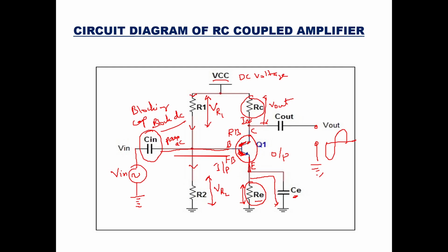So you are transferring from low resistance to high resistance. So it is transfer of resistance. Okay. Now whatever input voltage develops a base current here, that base current at the output, that is collector current here, will be in large magnitude. It will amplify because of the transfer of resistance action of the transistor, and transistor will amplify the output current. This current flowing through this resistance RC will develop a large voltage at the output. Hence, we say there is an amplified voltage at the output. So this is how your RC coupled amplifier is going to work. Okay. So these were the component description and working of the amplifier.